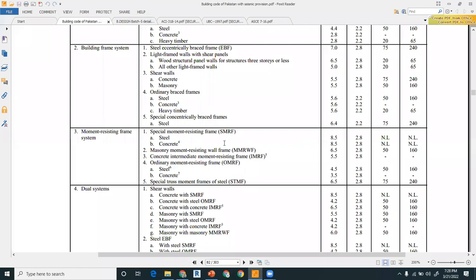For example, if you remember, the lapping criterion for the SMRF is that the distance between two stirrups in the column or beam, center to center, should not be greater than 4 inches, for example, right? There are many other requirements too: if you provide 6 bars at the top of the beam, you must provide at least 4 bars at the bottom of the beam, right?